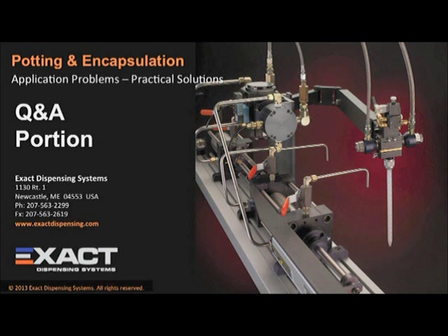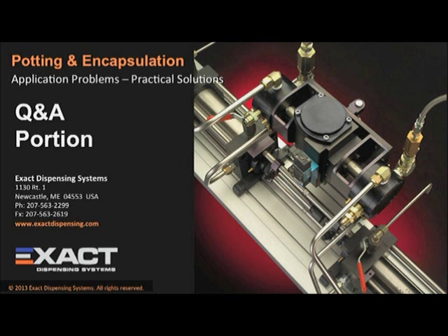Is it okay to feed materials from a pressurized feed tank with 80 psi of air or nitrogen? All liquids absorb gas. Some, like silicones, absorb air faster than others. This is not a serious problem with a single part dispenser, but in the two-part dispensing business, it's a big deal.